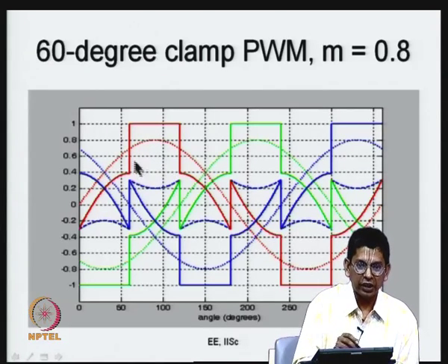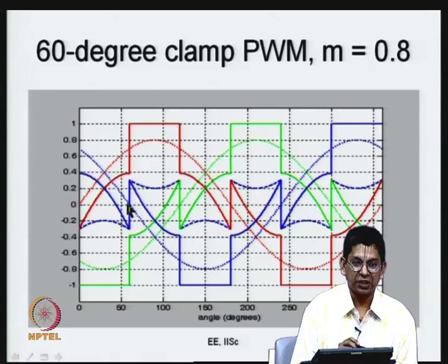So, whenever the R phase current is going through 0, the phase is not switching, and switching energy lost is proportional to the current it is being switched. So, the phase is keeping quiet, it is not switching when the current is going high, and therefore, there is a substantial reduction there now.